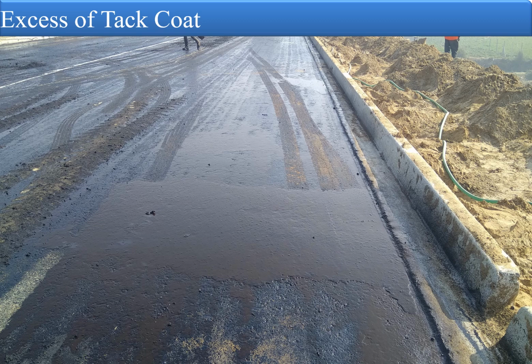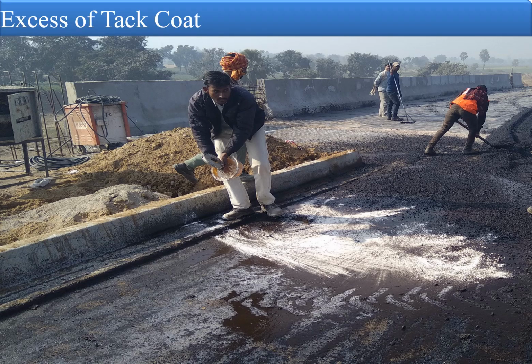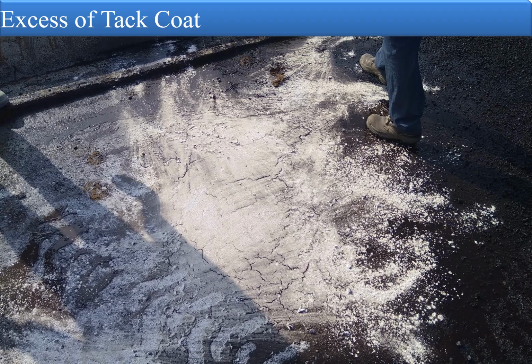So what is the remedial action one can take? You can apply lime or sand or some material which is absorbing in nature, so that the excess emulsion which is being applied is absorbed by the material sprayed over it. In this particular case, we have applied lime. So you can see the cracks clearly. That means the lime is being absorbed by the excess emulsion material which is laid at that particular site.